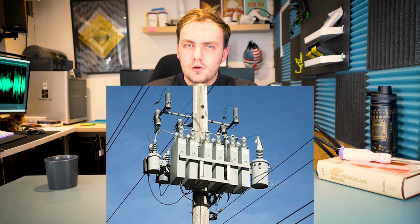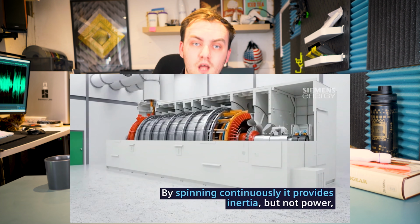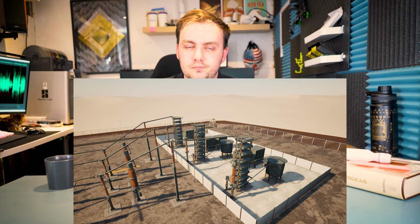You'll often find mechanically switched capacitor banks, or MSCs, in substations and smaller capacitors on distribution networks in order to add capacitance to the network during times of high inductive loads and to help balance the power factor caused by renewables. There are other solutions for improving power factor, such as synchronous condensers and certain types of harmonic filters, but we'll explore them in depth another time.